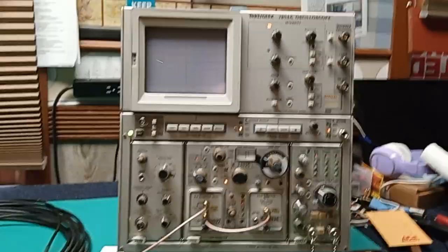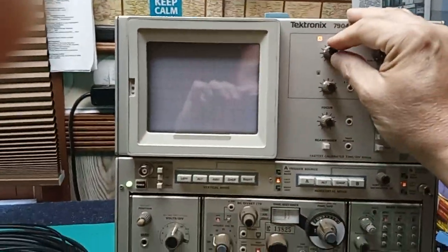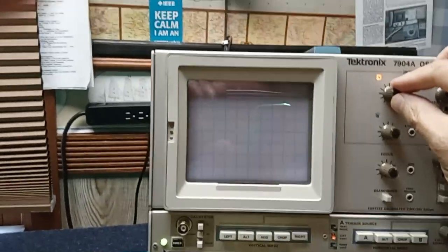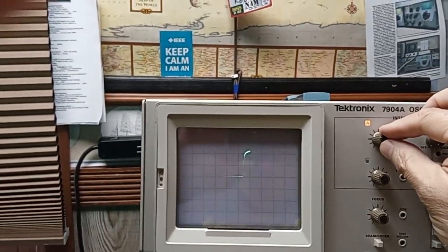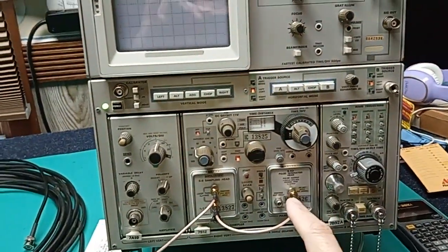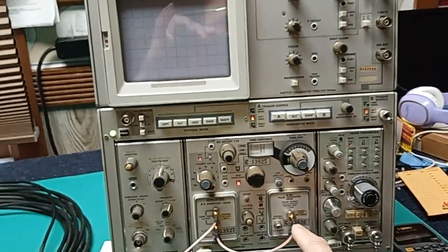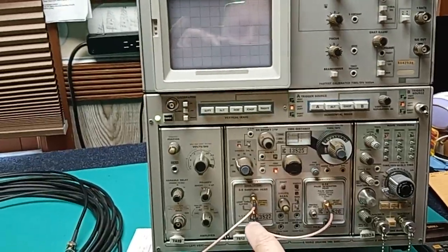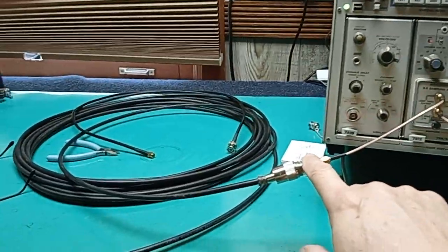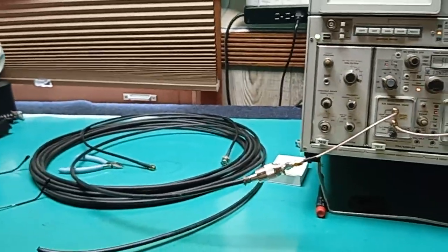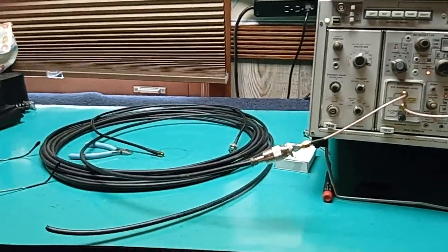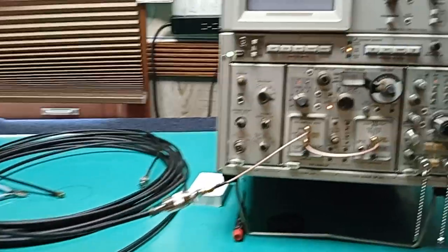And now on to a more serious topic. Working with the Tektronix Time Domain Reflectometer, TDR. The TDR makes an extremely high rise time pulse from a PIN diode, transfers it to this reading unit, out to the transmission line connected to an unknown length of cheap RG58. My goal here is to match the length of these two 50 ohm cables. It's not rocket science.